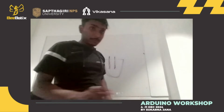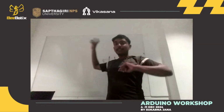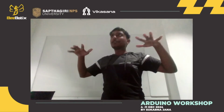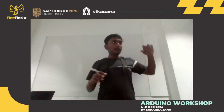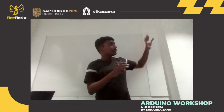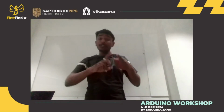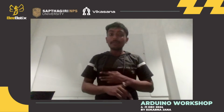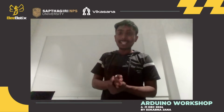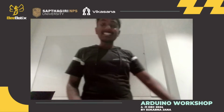One more example I can give is sunlight intensity. You want to make a machine so that whenever the sunlight rises, your home light automatically turns off. Or, for example, today it's a little cloudy and the room is dark. You can mark a level: if it is darker than this level, just turn on the lights. In this way, you don't need to manually turn the lights on and off. Temperature sensors and all those environmental sensors which take environmental data mostly give analog signals, and we have small onboard ICs to convert them into computer readable form. So I guess you got to know where we can use analog signals.